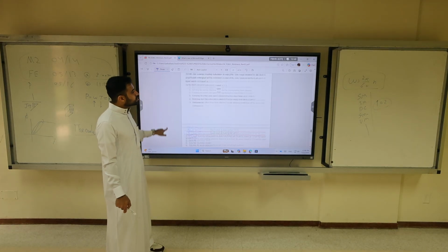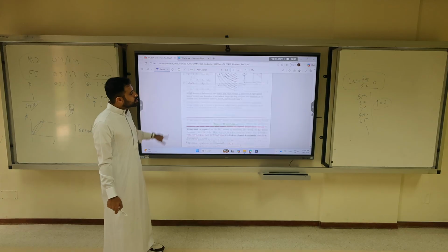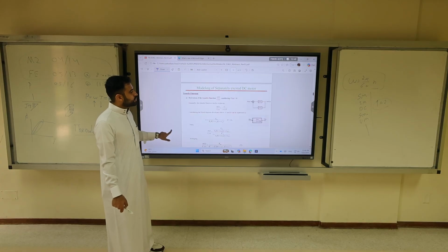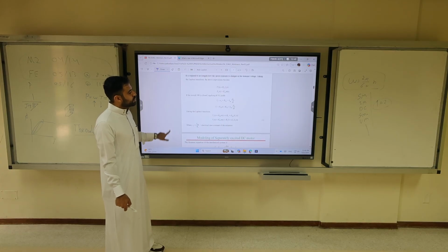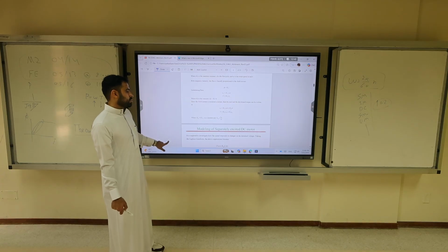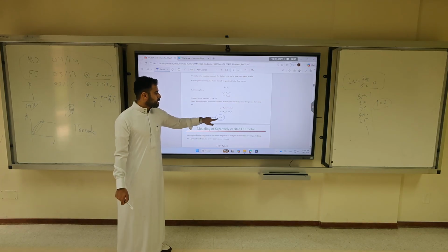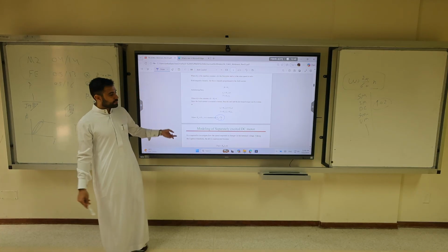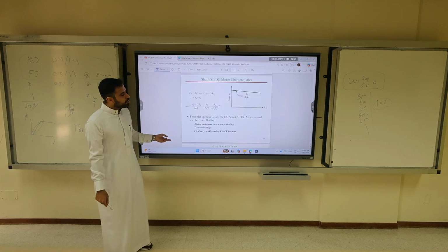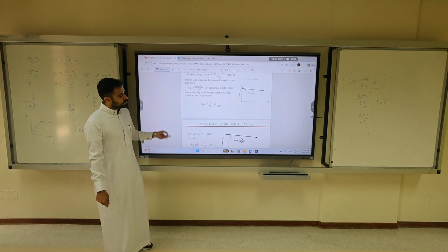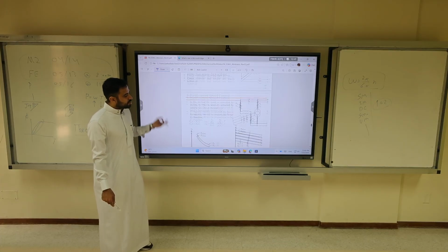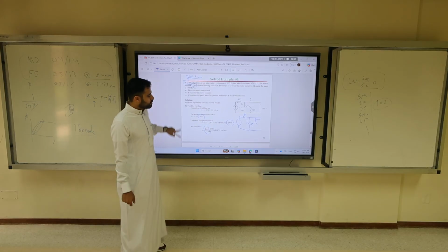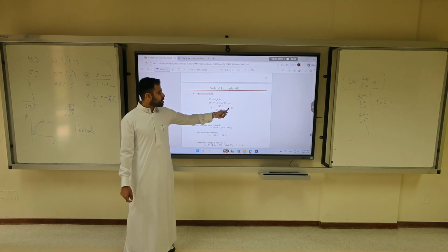So how do we get the constant? To get the constant, you have to go back to the original equations. It is this equation, the original equation on the first slide, before the transfer function. It is EA over omega. So 247 over 104.72. So what is the motor constant in example 1? This is solved example 1. It's going to be 1.187.